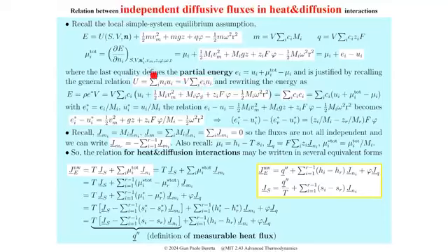So if you rewrite this expression for the energy, you write it here in terms of specific energy per unit volume times the volume. And here you substitute this for the internal energy, which is the first term here. So you see that the overall energy is given by a summation weighted on the concentrations of all these terms.